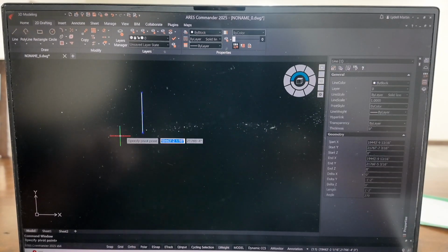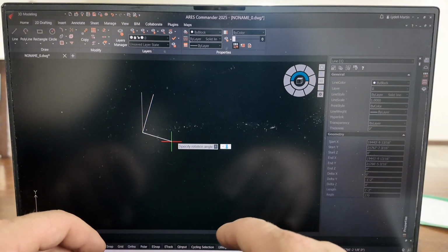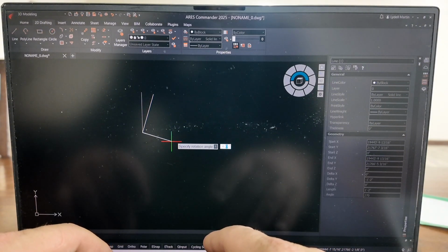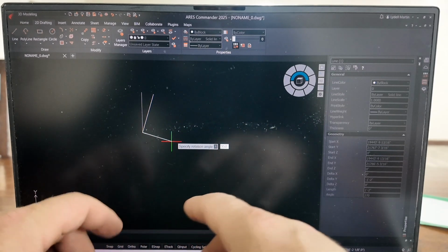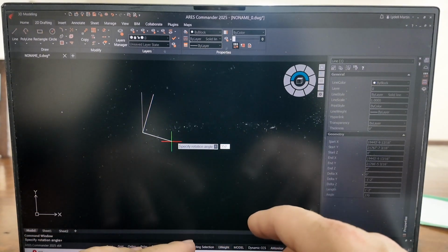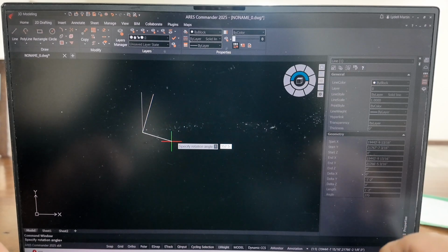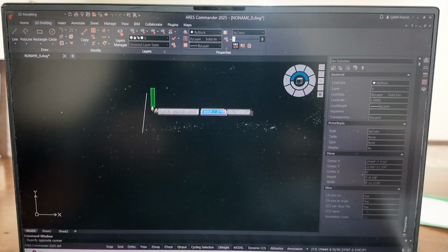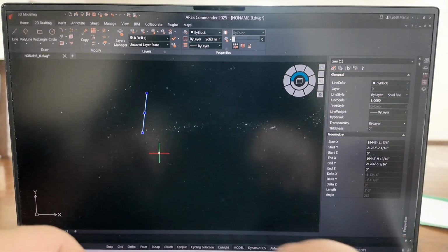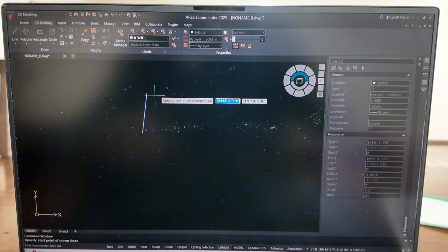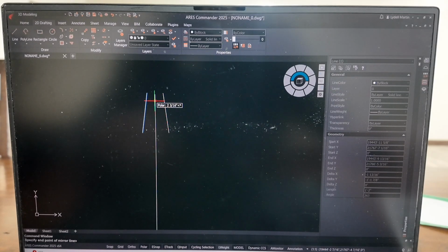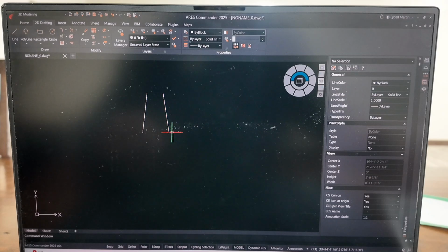Left click, right click, rotate. Select the bottom of it. And then 7.5 degrees off of 360 is 352.5. So we're going to type in 352.5, enter. We're going to select this. Now we're going to type in M-I-R-R-O-R, and we're going to select mirror. Then we're going to go up here just a few inches away, drag down till the other line appears, left click, go here and say no. So now we have these two.